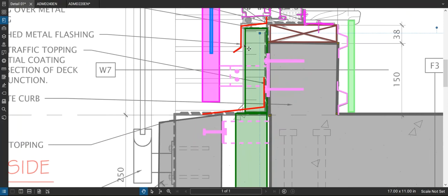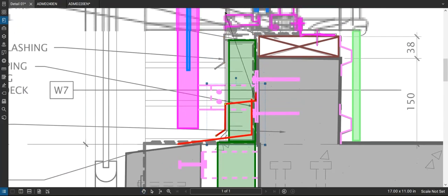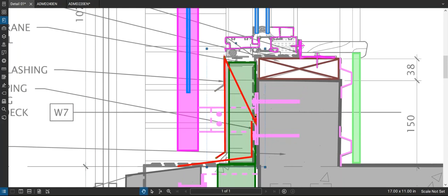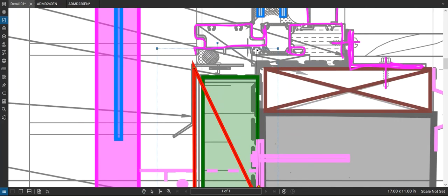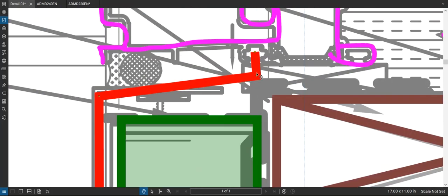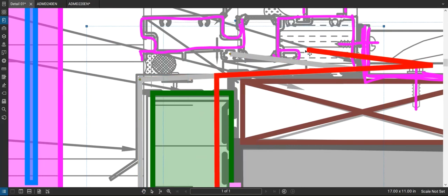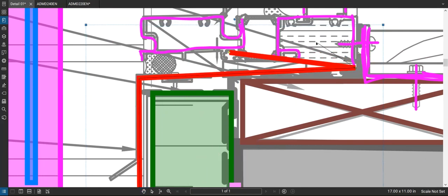And I think to finish this off here, looking at this, what I'd probably propose is that this come down like so. Just do it in one piece. I'm not 100% sure if the flashing goes into that point right there without having the manufacturer's literature, but if it didn't, you can extend it back, I suppose, and do this.